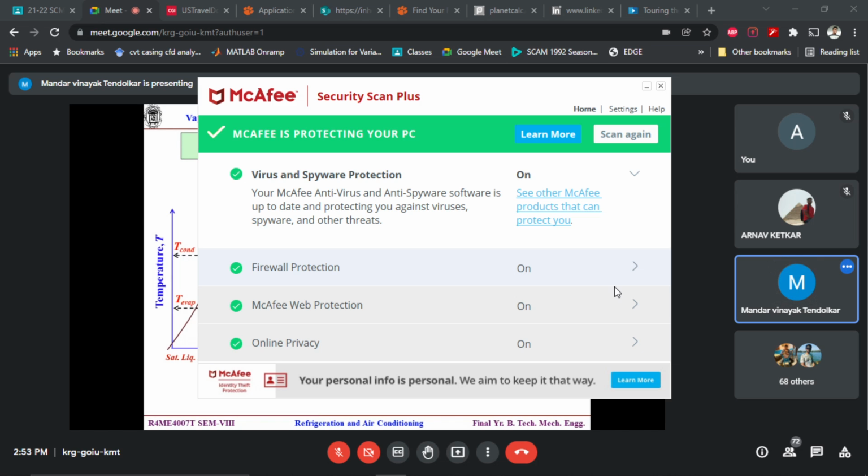So now you substitute the W's and the Q's, correct? W here you can substitute. For the VCC that is equal to, putting it all together, the Carnot work plus area A1 and plus area A2. This is also lost because it is the extra work for the compressor to be done. This is also a loss because this is the refrigeration effect which cannot be harnessed. So both are losses only. So both have positive signs. Plus area A1 and plus area A2. Do you agree?